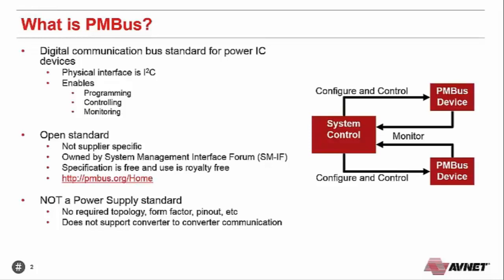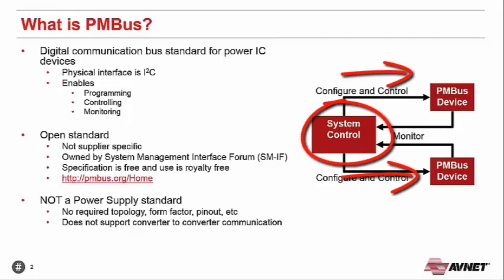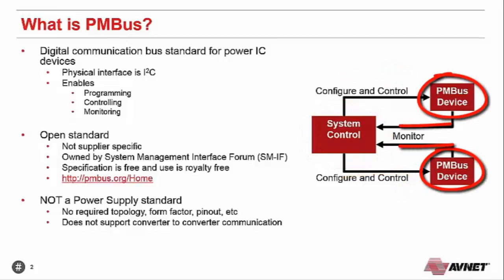So what is PMBus? PMBus is a digital communication bus standard for power IC devices. The physical design interface is an I2C. It enables things like programming, controlling, and monitoring your different power devices in your system. You can see from the block diagram, you'll typically have a system controller which can configure and control each of the different power devices, and you can also monitor their activity and performance from the system control device.